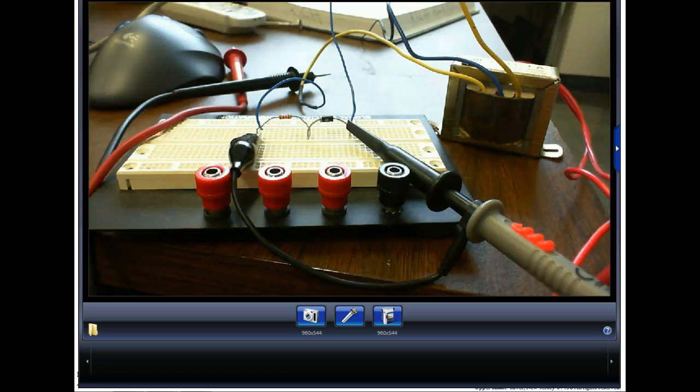That 12.6 volts is saying, okay, you'll get 12.6 volts if you're putting 110 volts on the primary, and you're loading the transformer to 1 amp. And what's the odds of me putting 110 volts on the primary? Exactly. What's the odds of having a 5% 100 ohm resistor that's exactly 100 ohms? Pretty low, right? But when we calculate it, we'll calculate it for what the transformer says it is. So when we calculate it, we'll use 12.6 volts. And by the way, this is a center tap transformer. And what does that mean?